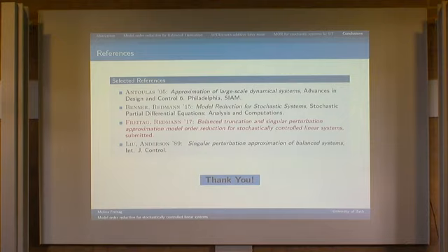Is that a minimum? Yeah, basically the A, B, and C matrices are sufficient to say if this system is controllable or observable. So the U, even though you can treat it as a control, is not really influencing the controllability of the system. So your A is symmetric positive definite here, right? Not the A. The A is just stable. So the eigenvalues have to be in the right half plane.